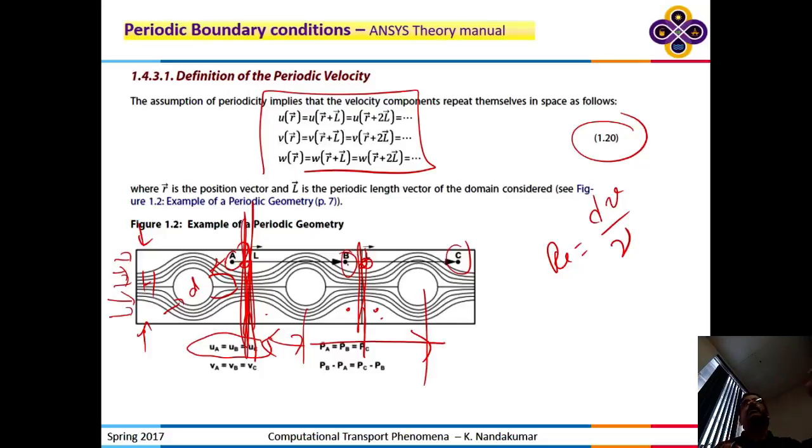Reynolds number as a concept is essentially a ratio of inertial to viscous forces. How dominant the viscous force is is determined entirely by the property. How dominant the inertial force is is determined by the velocity magnitude and some sort of a length scale.